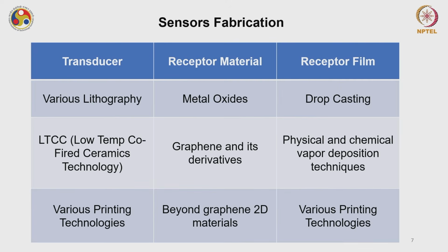If you are not aware of lithography, no worries, I will give you a basic overview of lithography. Then we have a very old technology known as LTCC, low temperature co-fired ceramic technology. This technology is also being used parallel to MEMS technology for transducer fabrication. And with the rise of printing, flexible devices, several printing technologies have also emerged as transducer fabrication techniques.